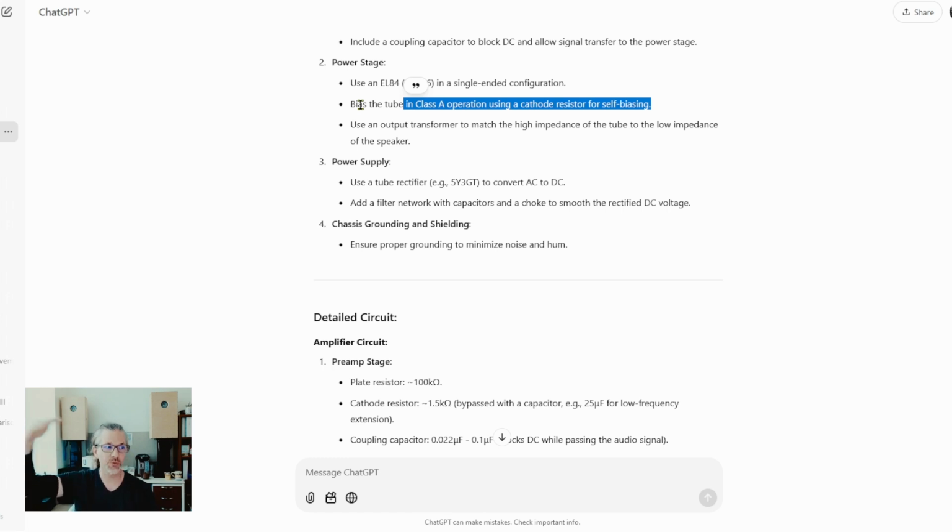But if you increase the B plus voltage to have the same plate voltage for a fixed bias as you have for a self bias, then the output power of the two is equivalent. So the reason to use a fixed bias to have higher power when you are a DIYer and you build your own is nonsense, because then you just increase the plate voltage to have that higher power, and you can have exactly the same amount of power.